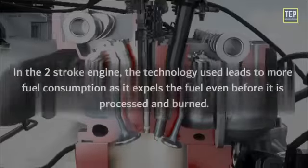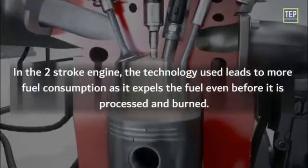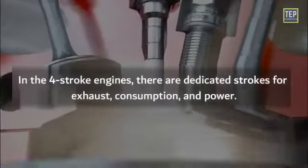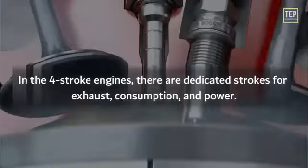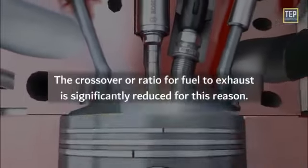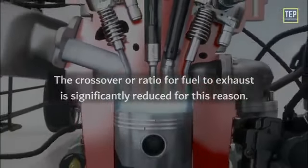In the two-stroke engine, the technology used leads to more fuel consumption as it expels the fuel even before it is processed and burned. In the four-stroke engines, there are dedicated strokes for exhaust, compression, and power. The ratio of fuel to exhaust is significantly reduced for this reason.